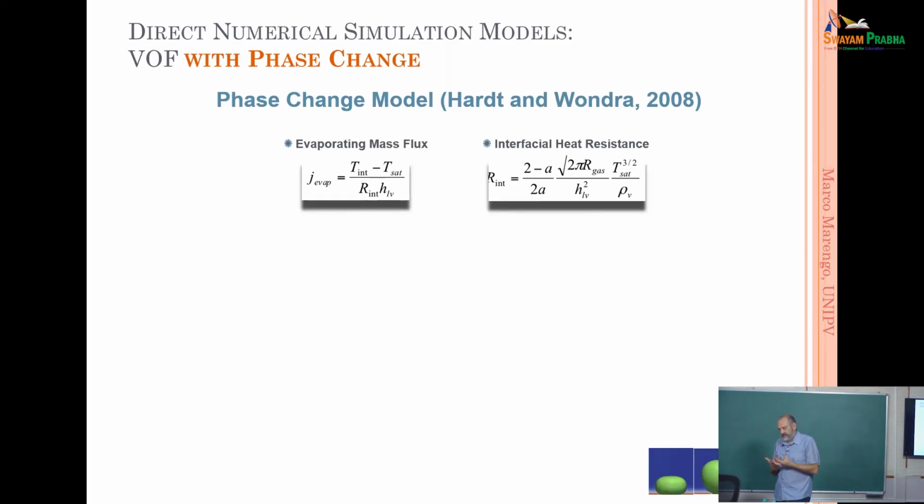So this temperature is the interface temperature minus the saturation temperature. So we are not considering metastable conditions. This is another point. We are in equilibrium. We are considering the saturation temperature. We are not going inside the two-phase region. Divided by what? Well, we can divide it by the latent heat, normally calculated at the saturation temperature, which is fine.